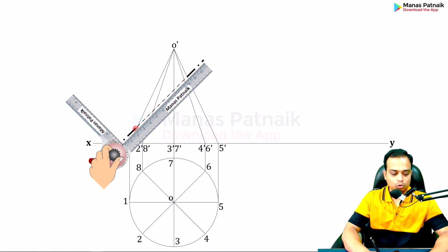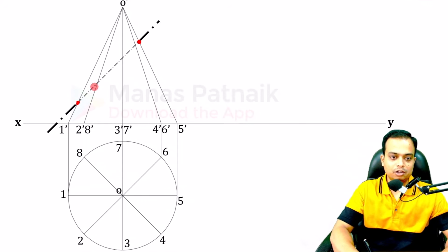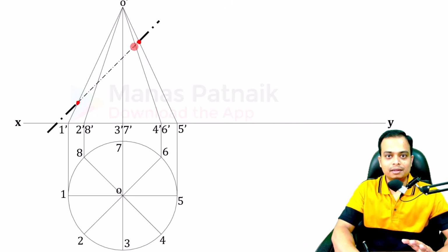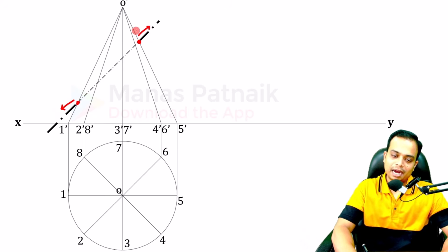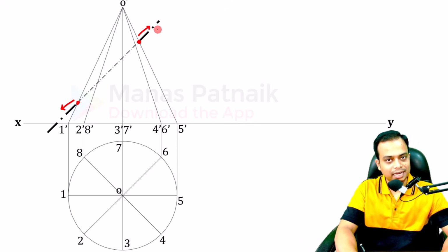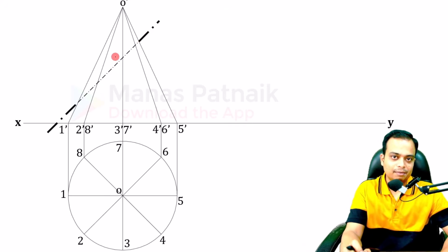Now, one thing that you all must notice, that between these 2 points, the part of the cutting plane is thin. Okay, it is a dash dot line, but it is thin. But beyond the cone, to the left and to the right, it is thick and dark. Dash dot, thick, dark, dash dot, thin and dark. So make sure you follow this protocol while making the cutting planes.